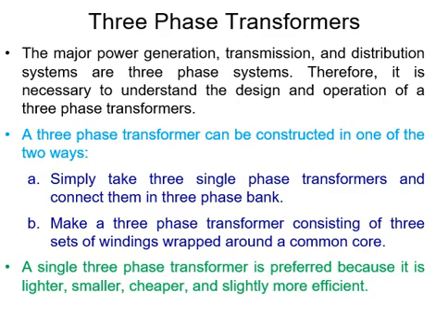If we want to know about the disadvantages of a three-phase transformer over single-phase transformers, they are a greater cost of standby units, and increased cost and inconvenience of repairs. In single-phase transformers connected to each other to form a three-phase bank, if one transformer is out of order, the other two would keep working. But in a three-phase transformer, if one transformer fails, the other two would not work and the whole three-phase transformer system will fail.